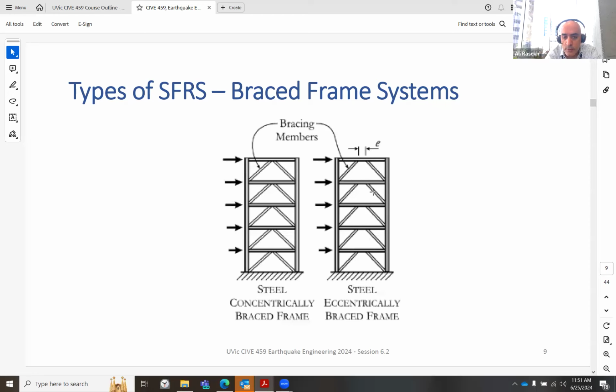And we will see that this one provides slightly better ductility to the structure, which means that more careful detailing is required with this one. But then you gain a higher reduction factor, so your earthquake load would be smaller because of the ductility that is provided. This other one could be designed or constructed in a more traditional way, and it provides ductility, but less ductility.